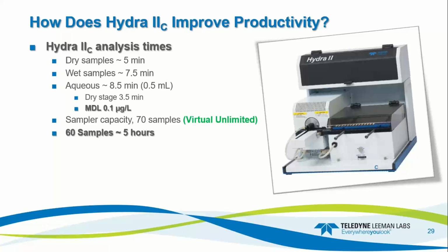And then I also run an external dryer with that system to help mitigate transient moisture through the system, which can disrupt the optical cells because water vapor has a myriad of absorbance lines, so you can get slight false positives from the water vapor within the system. So it's important to mitigate that as well. For petroleum distillates, volatile samples, that's about 11 to 12 minutes per sample. So you can also do those, but it takes a bit longer.